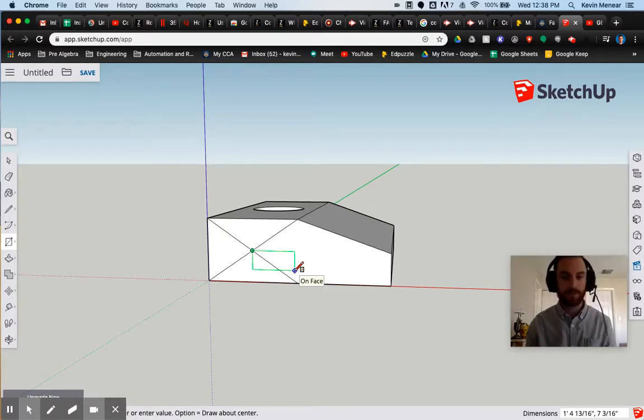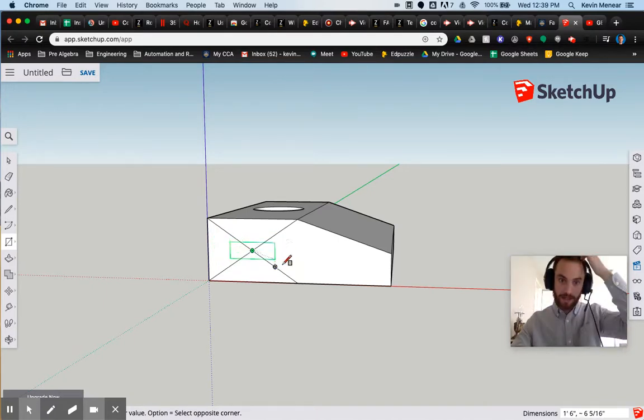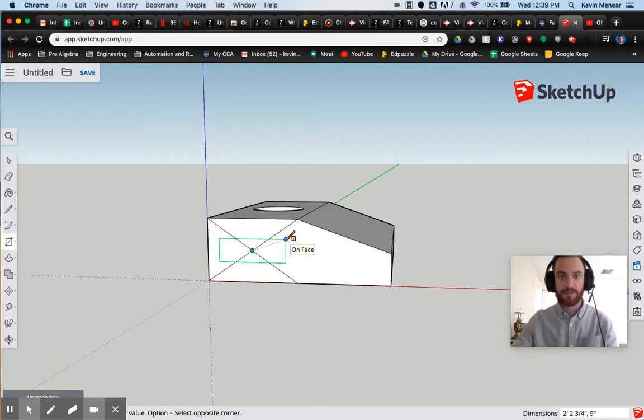That's the big question. Well, I just hit the Option key. That's what it is on the Mac. I'm fairly certain it's the same on Chromebook, but it might be different. If you see that it's not the same, then please don't worry about it. Just create a rectangle here and I will work on that another time and let you know. But the point is when I hit Option, boom, it's now created a rectangle with its center at that point.